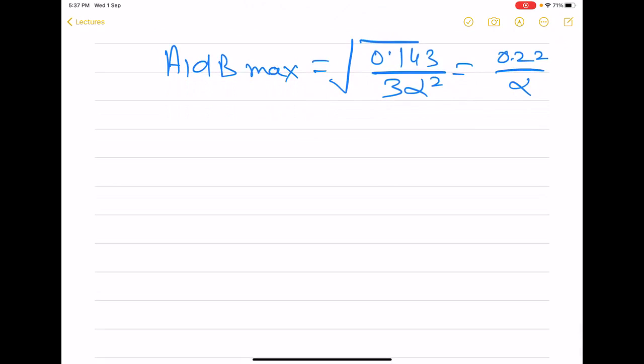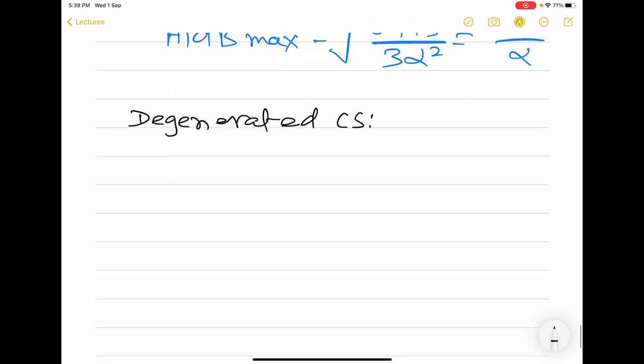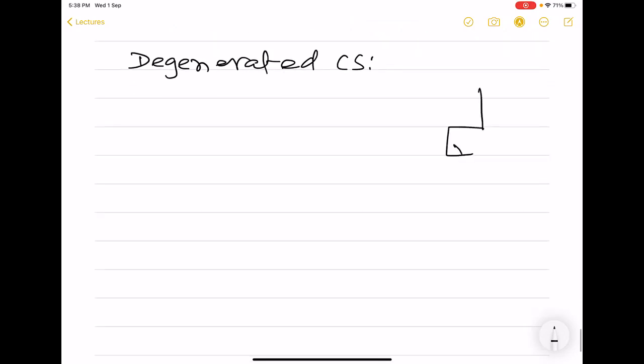Now we again get the nonlinearity, third order nonlinearity, even if we start with a simpler and well-known expression for the drain current, but we take the degenerate case for the CS. So in this case, source is no longer grounded, rather it is connected to ground via resistor.